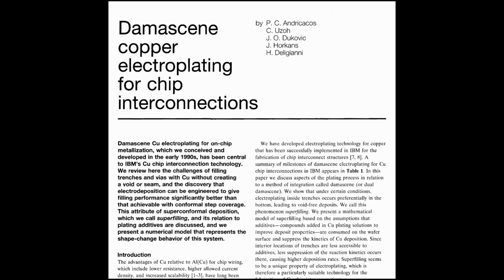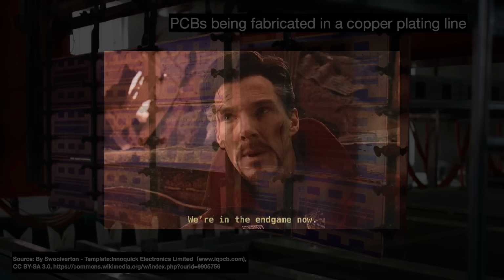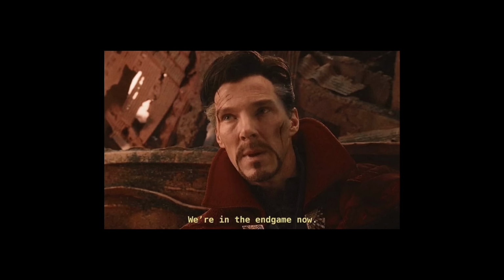We produced aluminium metal layers in a subtractive manner, so depositing a blanket aluminium layer, patterning the wires using photolithography, and then dry etching away the excess. Subtractive methods work great, but are incompatible with copper because the pesky metal diffuses into stuff. So IBM and others switched from a subtractive to an additive process, inspired by how they once made high-end circuit boards. We're in the endgame now, so let's finish strong.